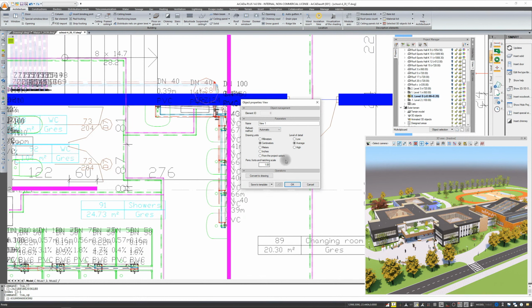Now here, the drawing units. By default, ArCADia draws in centimeters, which means that whether you insert a wall at the very beginning, or an electrical outlet, for example, or a wall in the external sewage system, you draw it in centimeters. So if you are drawing external installations or networks, you should rather switch to meters. Take the view properties and switch to meters from centimeters, so that you do not have to enter data in centimeters when drawing in the terrain.